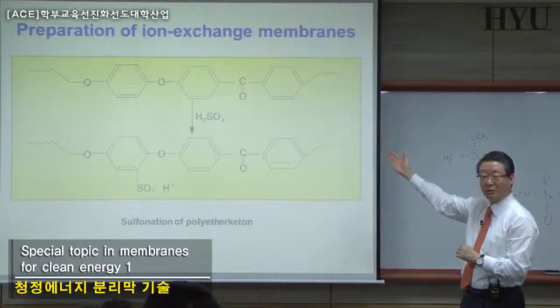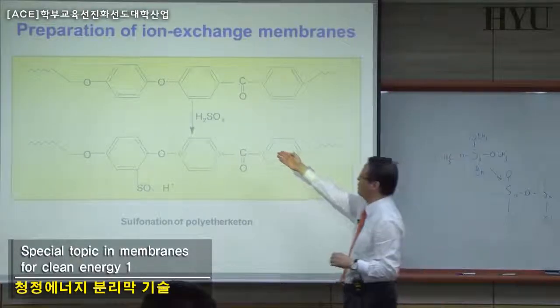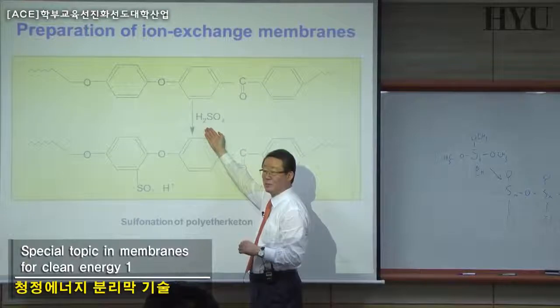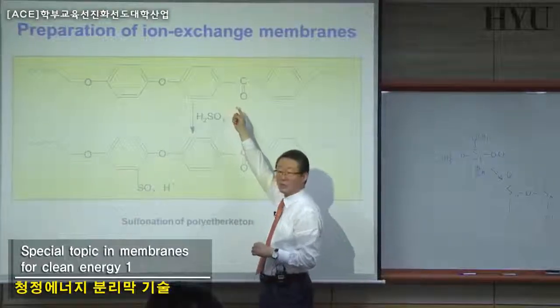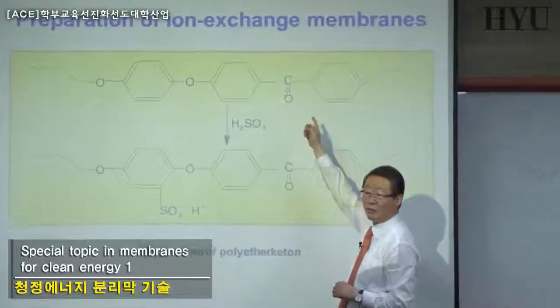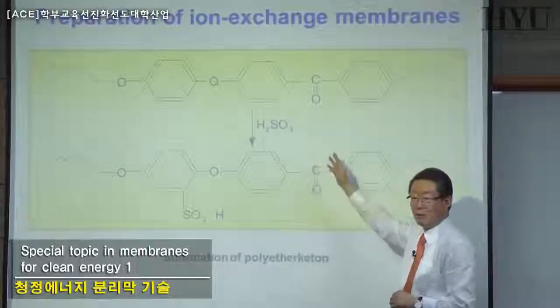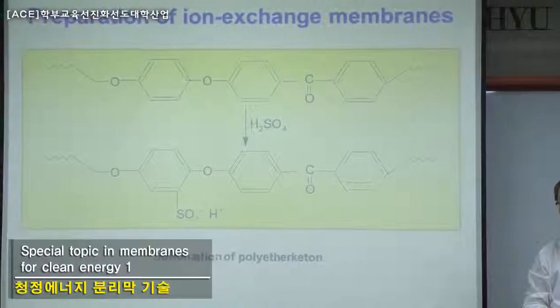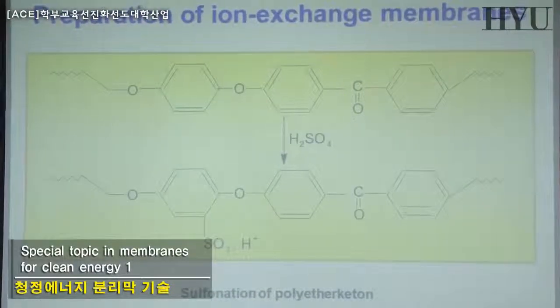Homogeneous reaction is quite difficult in this case because we have to use the aqueous phase, whereas this PEEK is not soluble in the aqueous phase, soluble only in the organic phase, and it's not miscible at all. So the homogeneous reaction is not possible, and the heterogeneous reaction causes some unreacted PEEK. So the yield of this S-PEEK was not what we had expected.